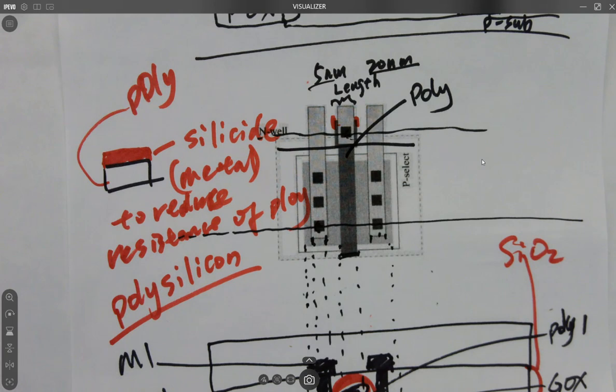Is there always a gate oxide under poly? Good question, actually. If you are not using that as a gate, do you still need that gate oxide or not? I don't know. There will still be an oxide layer under the polysilicon. If you're not using it as a gate, probably not. If you're just using poly and another layer of poly to form a capacitor,